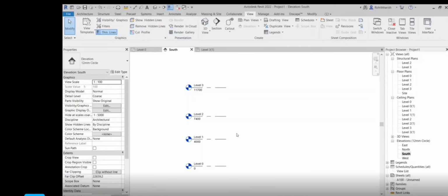We have to select the structural plans, then we will add it. From where? From view. Right. So simply go to view, plan views again. Here I want to work on structure. I want to add levels in structure. I'll select structural plans.